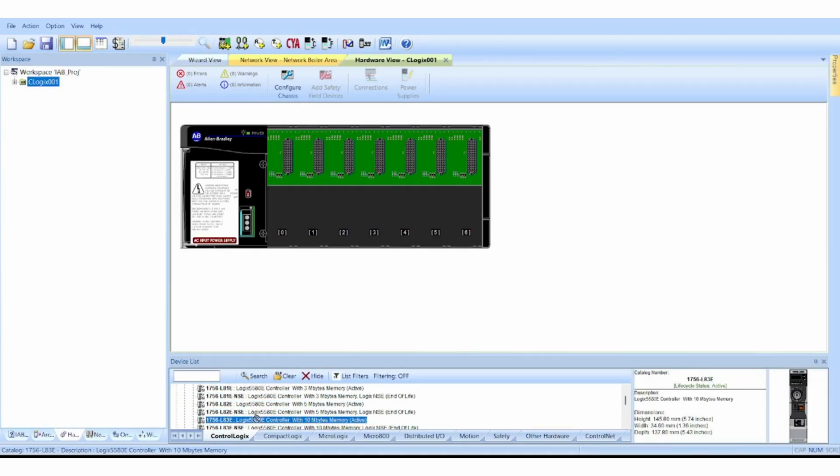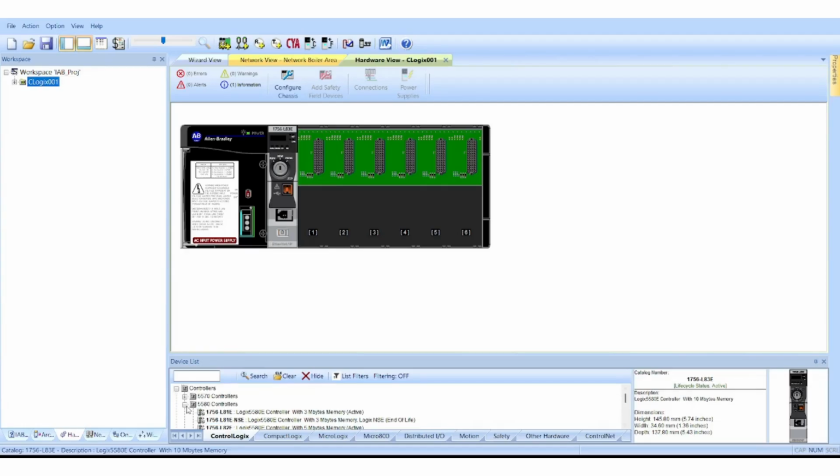Another important decision is that we are not trying to control the complete refinery with one large processor. The refinery is naturally divided into different process areas. Therefore, where required, the control application can also be logically distributed across multiple processors.